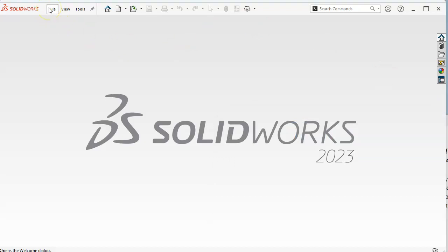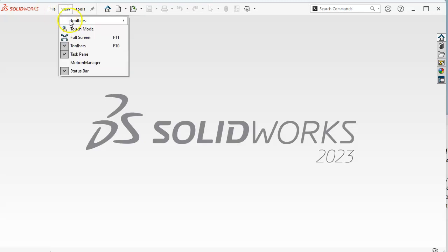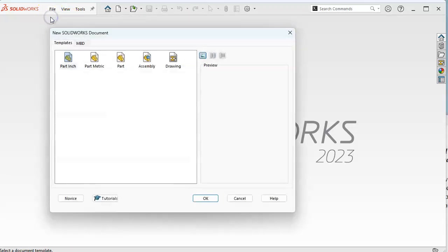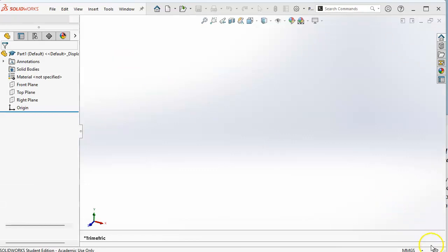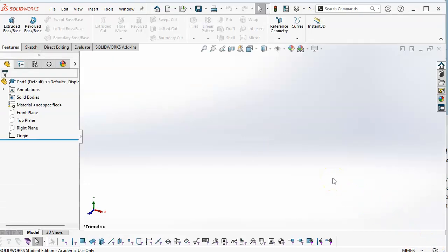Okay, so to start off with, we're going to follow these same procedures through all of our models. So File, New, and we're going to be opening up a part. If you created the templates, then part inch and part metric are the default templates, and I'll assume that you haven't, so we'll be in millimeters and grams and seconds. And for this exercise, it's not really that critical. So to save a little bit of time on the files, I'm going to use solid bodies.